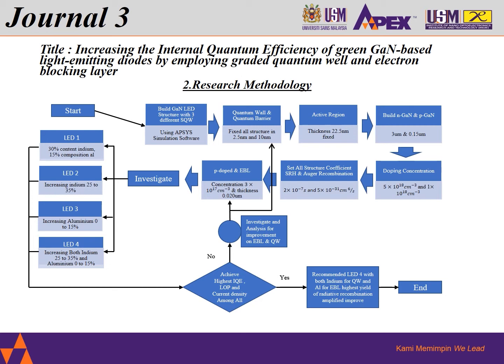And next will be the p-doped EBL. Then the concentration will be set to 3 times 10 to the power of 17 cm to the power of negative 3, and the thickness will be 0.020 micrometer. After completing all the structure of the GaN-based LED, we'll start the investigation.